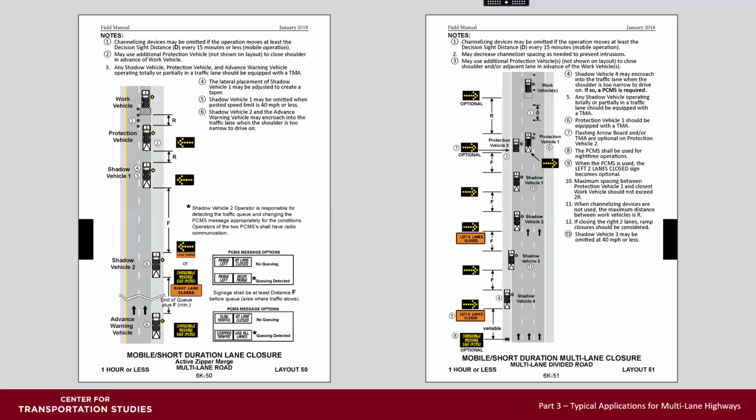Note that the devices in this layout are all vehicle mounted, such as in mobile operations, but this is for a short duration of 1 hour or less. Also important to note that if it moves beyond decision sight distance again, the channelizers may be omitted.